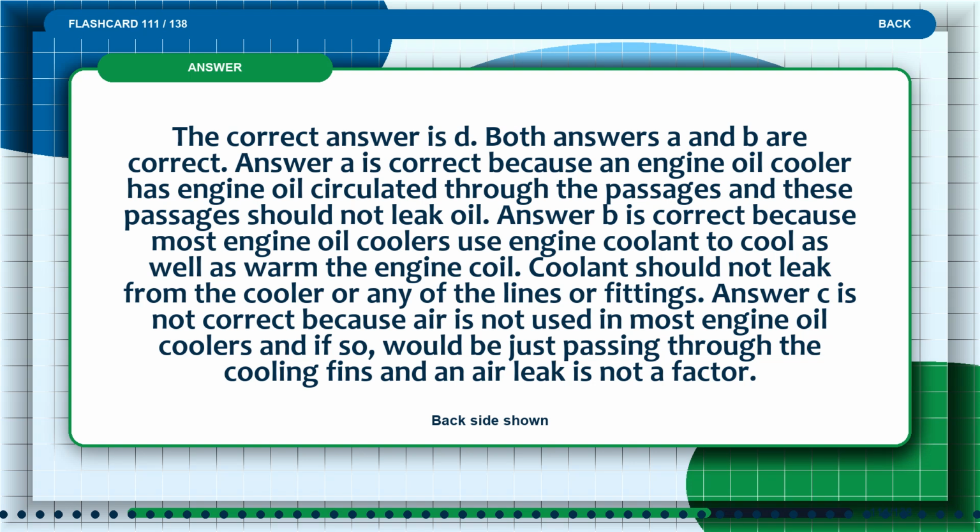The correct answer is D. Both answers A and B are correct. Answer A is correct because an engine oil cooler has engine oil circulated through the passages, and these passages should not leak oil. Answer B is correct because most engine oil coolers use engine coolant to cool as well as warm the engine oil. Coolant should not leak from the cooler or any of the lines or fittings. Answer C is not correct because air is not used in most engine oil coolers, and if so, would just be passing through the cooling fins, and an air leak is not a factor.